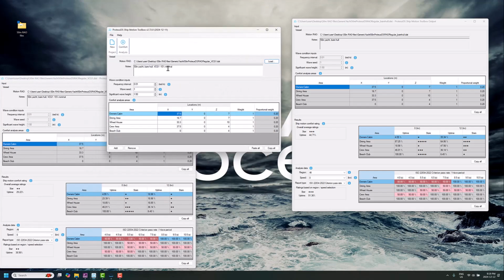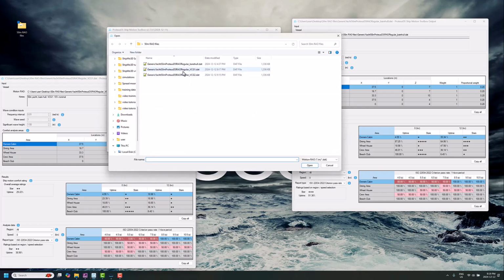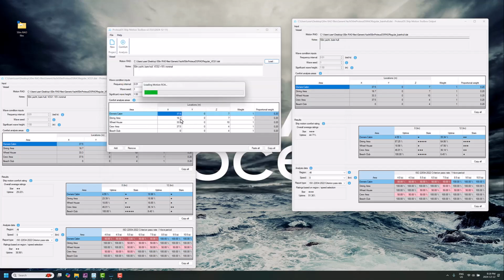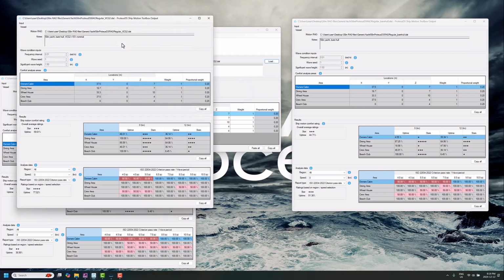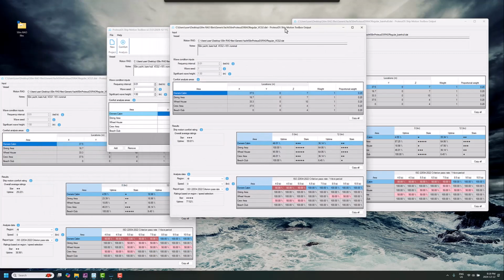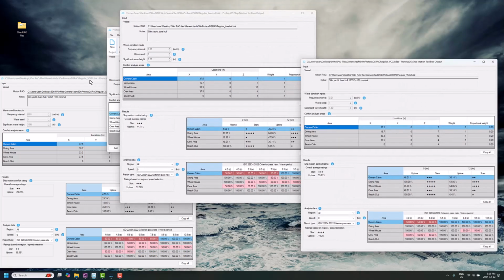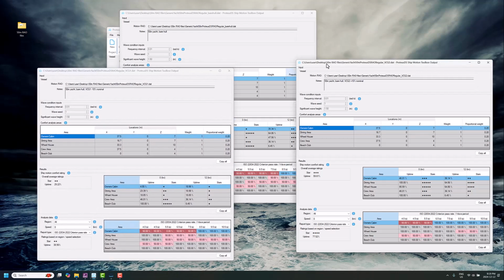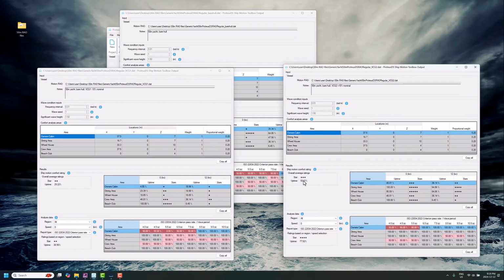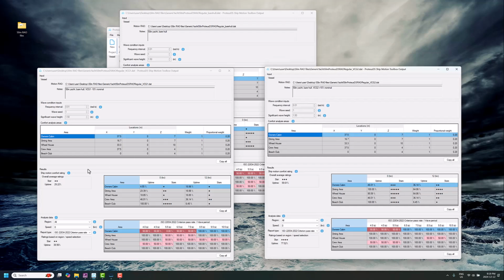On the other hand, we should also see a difference when we look at VCG2 where we go plus 10% nominal. So we'll load the other motion RAO database here, and we'll run the comfort assessment. And so we see a huge improvement in comfort as well. I know it's a lot of numbers we have in front of us here. What I wanted to draw attention to is the difference between the really high VCG value, low metacentric height, where we have a really high comfort value, and then the lower VCG value, higher metacentric height, where it's more stiff.